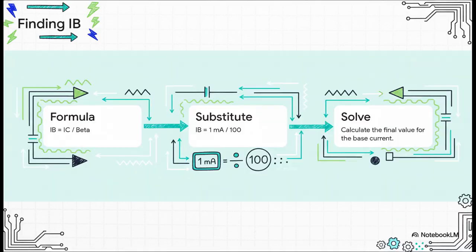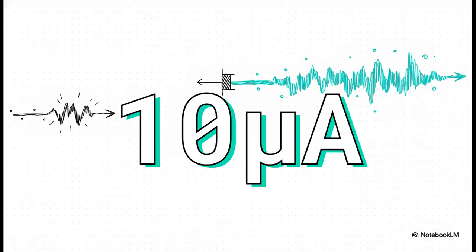Simple as that. Okay, so we just figured out the collector current is 1 milliamp, and we know from the givens that our beta is 100. So we're just going to divide 1 milliamp by 100. And we get 10 microamps. Now just think about that for a second. A microamp is 1 millionth of an amp. This is the incredibly small little trickle of current that's controlling that much larger 1 milliamp current at the output. That's the amplification we're talking about.